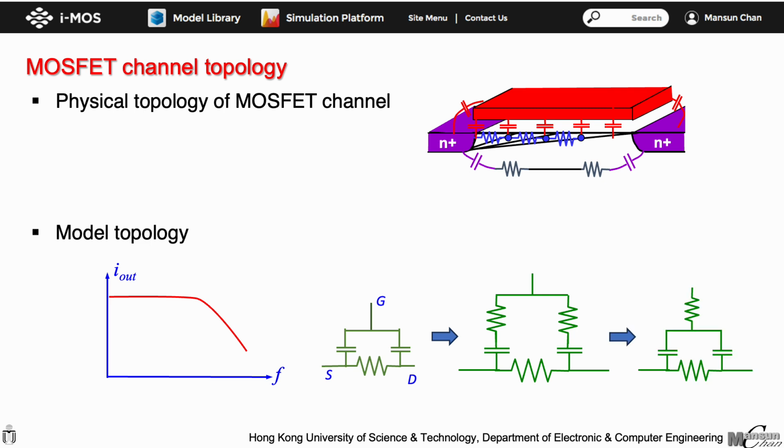Or an even simpler method is just to add the gate resistor to generate the delay due to the dominant pole of the distributed network. By adjusting the resistor value, the location of the dominant pole can be matched. The process ignores all the high-frequency poles, but it is acceptable as we seldom operate transistors beyond their unity gain frequency. At the same time, the practical operation frequency of the transistors of many circuits is determined by the external components that they are connected to.